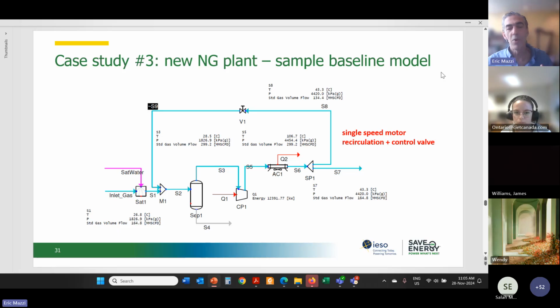It's the same process that we've talked about with the oil pipeline and effectively with the water treatment. You take the as-built plant, you build a model of it, and you calibrate that model until it agrees with the metered consumption, both in total and for some individual major motors, such as the 31,000 horsepower motor. And then there is a targeted calibration error of, I think we went with 5% in this project.